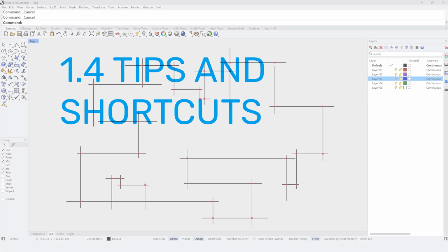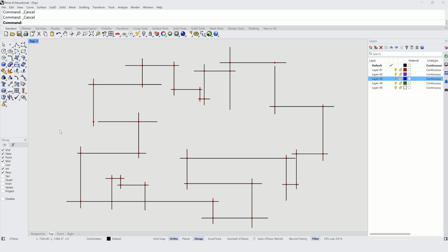This video introduces tips and shortcuts that will speed up your actual work sessions. Let's say you need to chamfer this collection of curves wherever there is an intersection. To do that, go to the toolbar, cascade the menu below, Fillet Curve, select Chamfer, and finally complete the operation.